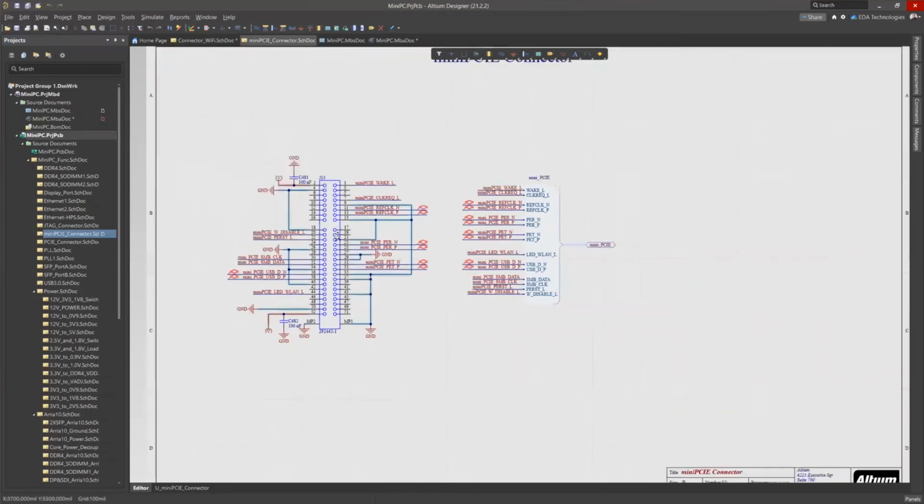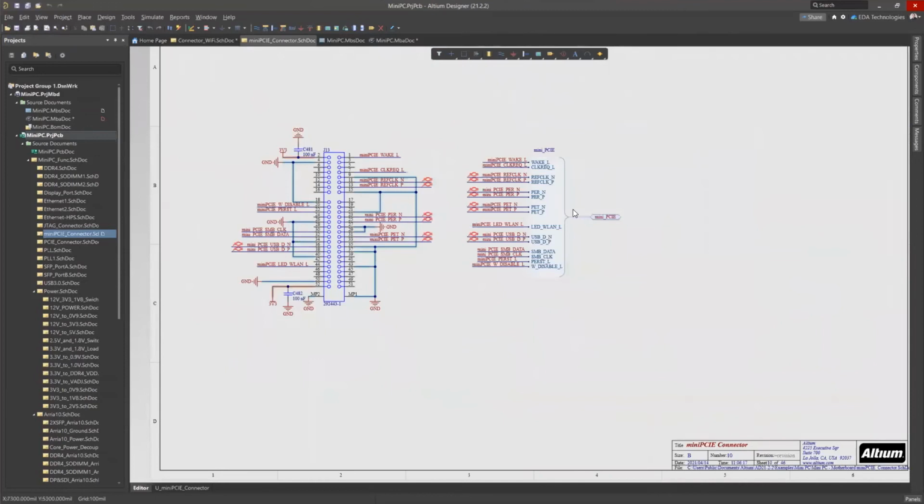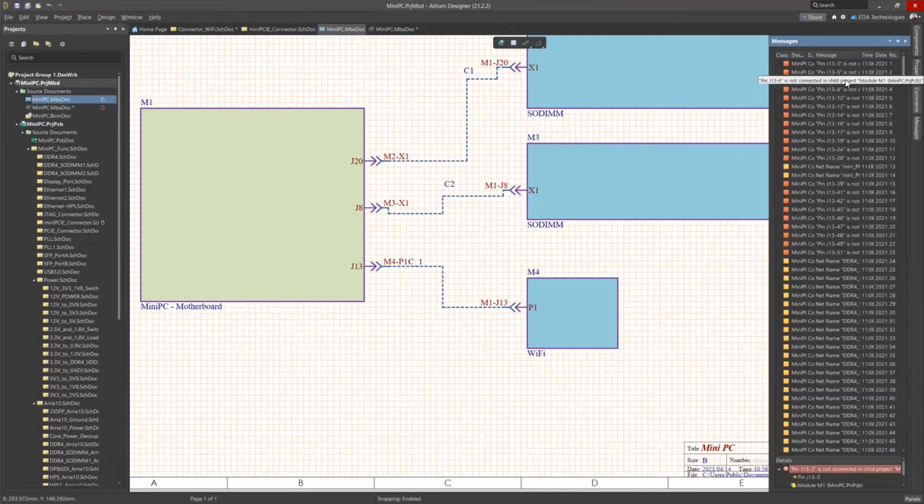So here you can see the USB comes in onto these and would connect to this. And then that obviously goes through a bus, or a harness, into another connection on the top level. So what Altium can do is, if I say, for instance, run an ERC, here you can see it's saying, okay, these pins aren't connected. There's a bunch of net names that don't match, etc. These are checks that you need to clear yourself, unfortunately.